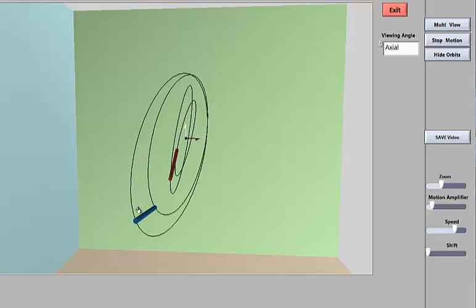So here it looks like the blue shaft is very, across itself, very in phase, so it's all moving in one direction, which tends to point towards a type of imbalance characteristic. And that's probably also likely because the orbit seems to be relatively circular, which is pretty characteristic of imbalance.